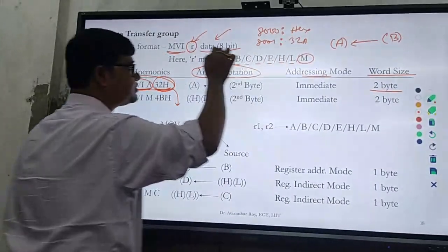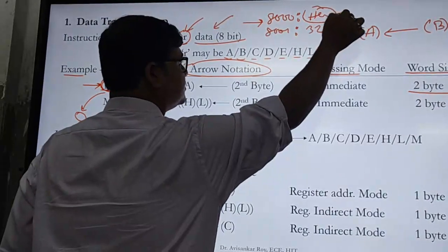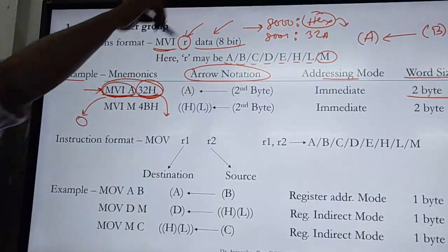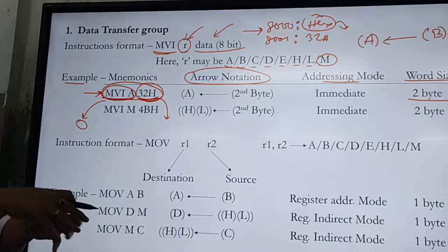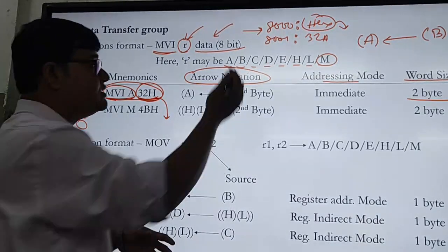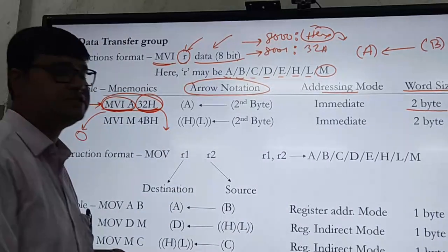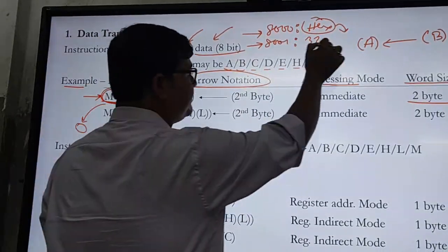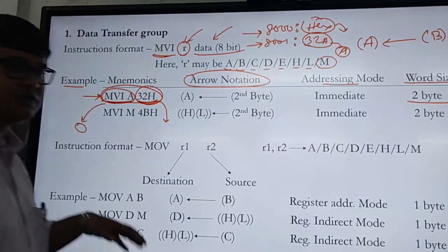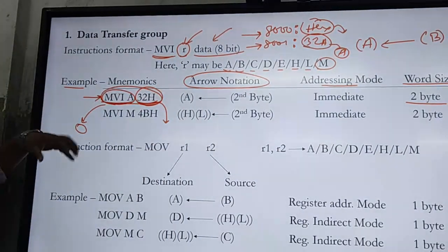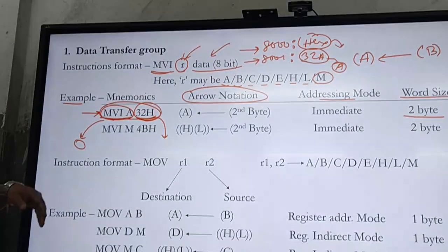So whenever the microprocessor goes to 8000 and takes the hexadecimal code and decodes it, it understands, okay, here is the instruction where some 8-bit data can be loaded into the accumulator. Which data should be loaded to the accumulator? To find the particular data, the microprocessor has to go to the next memory location, that is 8001. So 32 can be found and loaded into the accumulator, right? So this is actually the function and working flow of how the microprocessor executes a particular instruction.